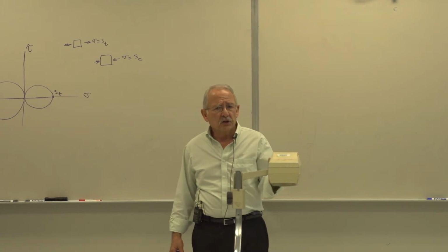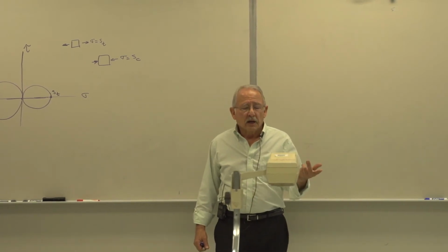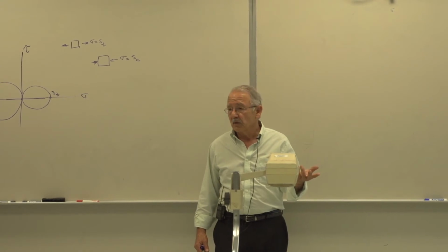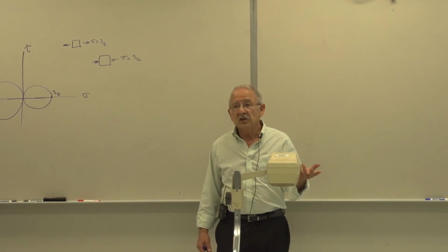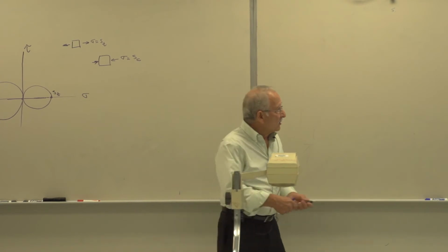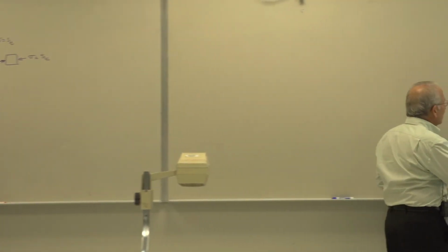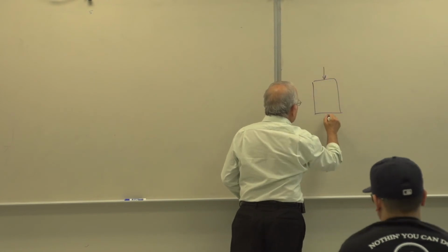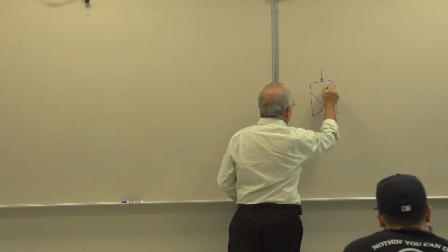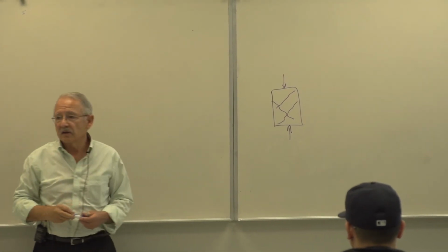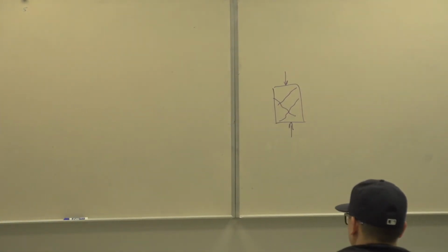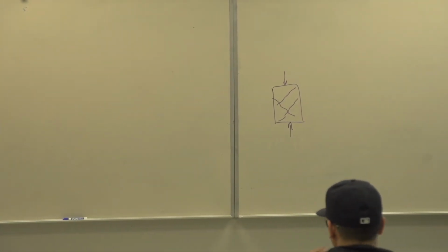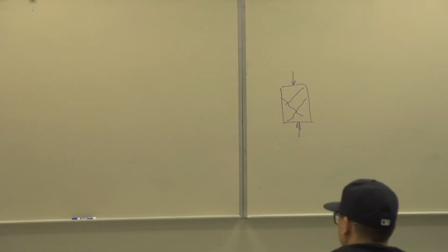And if you've worked in the industry anywhere, and if you've seen concrete, for example, tested in compression, you see that it essentially shatters along 45-degree lines, the direction of the maximum shear stress. All brittle materials do that. Okay, so we got these two.